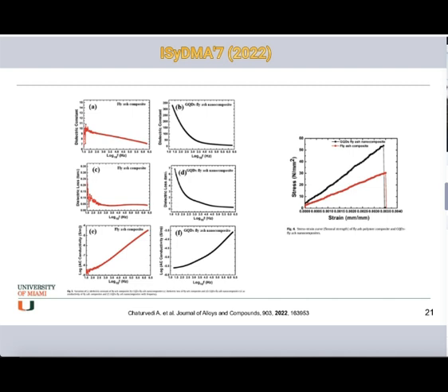To conclude, for the dielectric work that has been published this year and last year, a high dielectric constant of 350 was observed for the carbon dust nanocomposite compared to 10 for the pristine fly ash composite. The strength of the carbon dust nanocomposite was drastically enhanced by the reinforcement of carbon dust, with a high flexural strength of 60 megapascal compared to 35 for pristine.